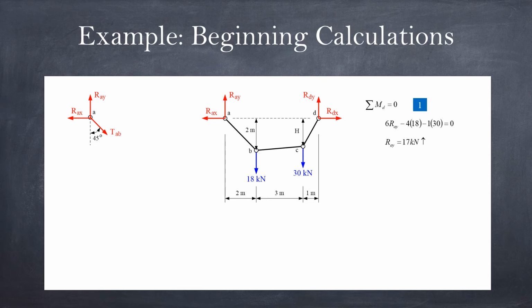If I have RAY, then in the y direction, still on the right-hand side free body diagram from A to D, I can do sigma Fy, because then I have only RDY left in the y direction. So there we go. Now I have RAY and RDY. Now for X, there's no point doing it because I have 2 unknowns and 1 equation.